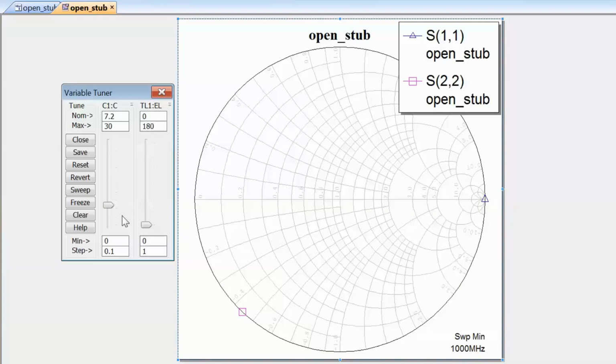We can also see that since we're looking at the impedance chart, as we increase the capacitance, we are actually decreasing the impedance in absolute value. And that's because the reactance of a capacitance, which determines entirely its impedance in this case because we are looking at a lossless case, is 1 over omega c, and hence it is inversely proportional to the value of c.